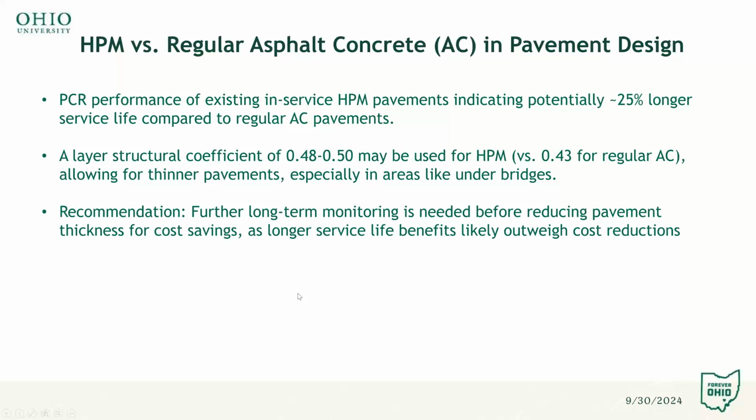Particularly from the field performance, we realized that we probably should not reduce the surface intermediate course because we are using high polymer mix, because they don't perform very well. Even though this material is very tough compared with conventional material, you need to give them enough thickness for them to perform well.